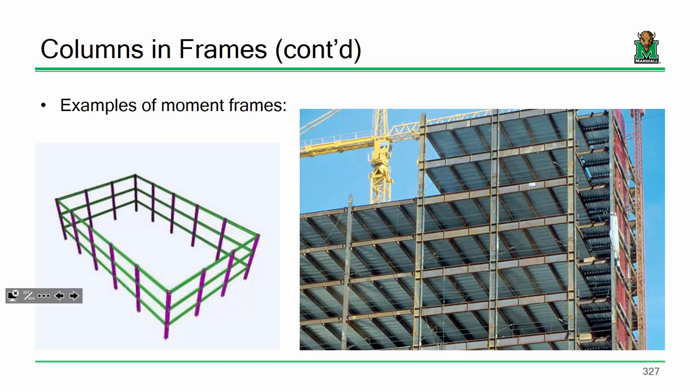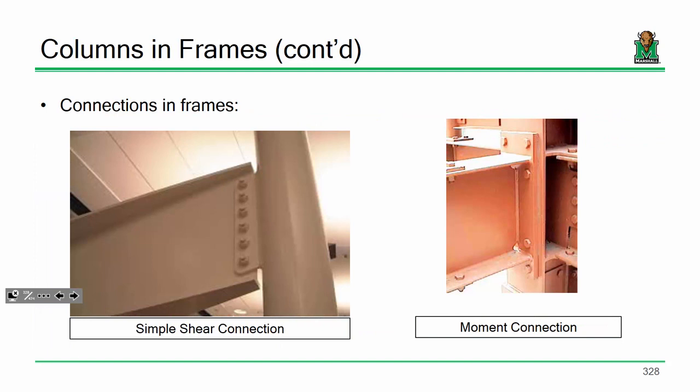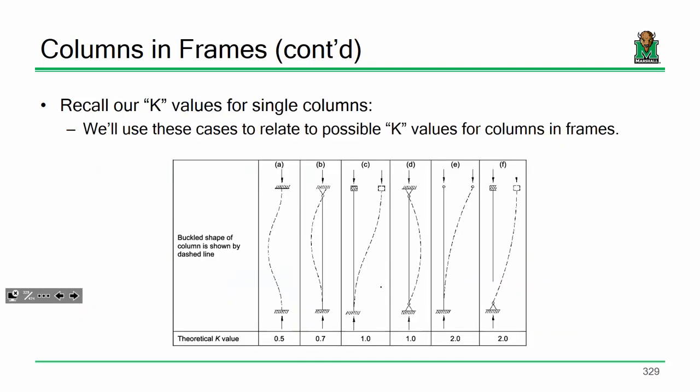force here and a large concentrated force here. Those plates are there to help stiffen that column against those concentrated loads. So you got to put them there too. If you notice, you can kind of see them. You've got something here and something about right there. Make sense? There's a lot more fabrication that goes along with the moment. Granted, you get a lot more open space, but there's a trade-off. It's a little more expensive. So it's all about what makes sense in the long run. Okay? Sound good? All right.